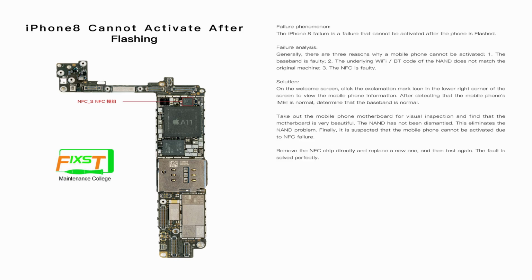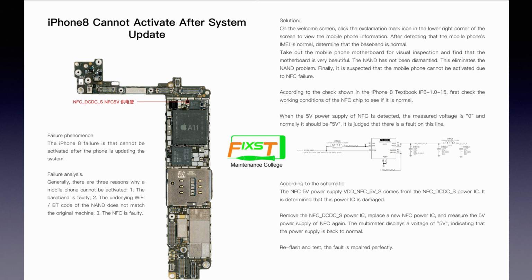We found that this motherboard is very clean and the NAND has not been removed before, so it's not a NAND problem. So we judge that this problem is caused by the NFC. We carefully remove the NFC IC and change a new one. Install and test the phone again. This problem is solved. This is the iPhone 8.